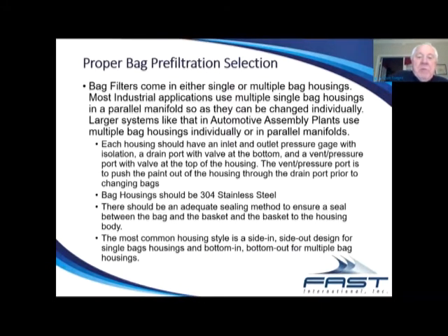Also, bag filters come in different size housings, from a single bag housing to multiple bag housings. Most industrial applications or the custom coater applications use single bag housings that are in parallel manifolds so that they can be changed individually. Some of the larger systems, such as automotive assembly plants or large tanks, will use multiple bag housings. So multiple bags in individual housings. They'll also be sometimes connected either individually or in parallel.